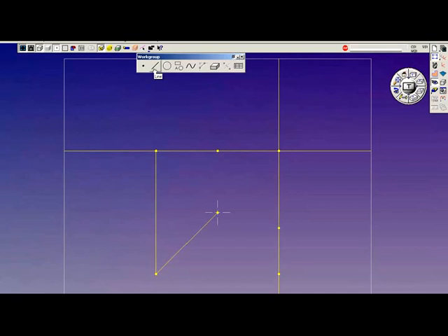Okay, back to the line creation tool. A line at an angle through a point. Now, previously, with Control L, we saw reference labels. If I want a line at maybe 30 degrees, or let's say 35 degrees to a given point, I select the point, and I see the label in the text input. See that? P7, P7.